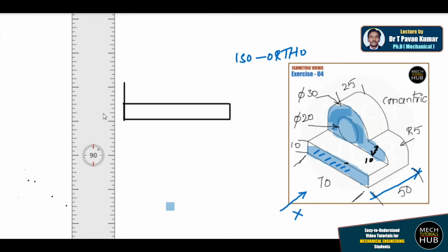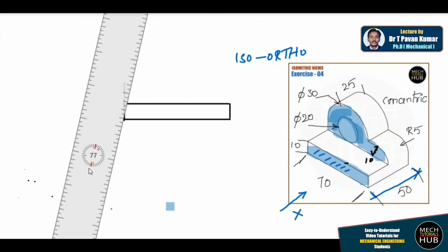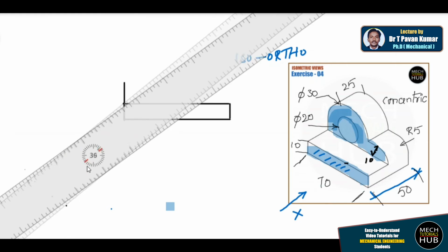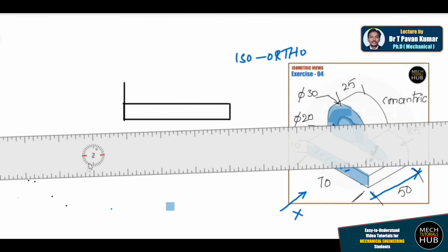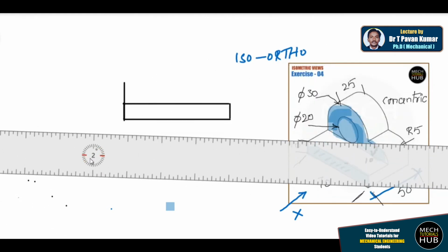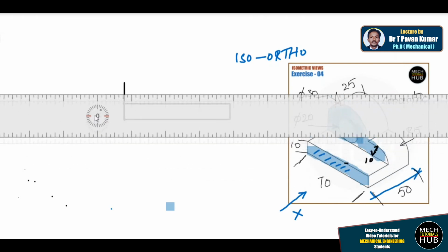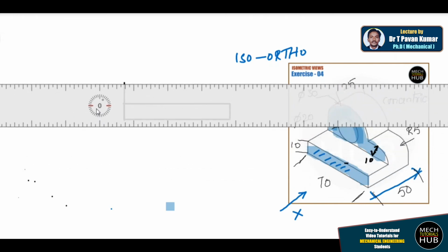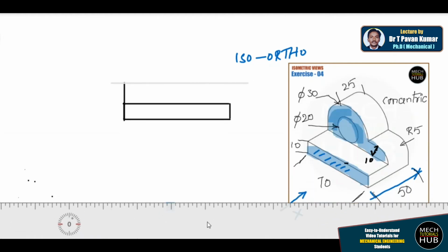after this, with the help of compass, by considering a locus, I'll tell you how to draw a locus line. Locus line is nothing but a reference line which will help you to draw further features or the lines or the links. I'll try to place a scale at the end point of the intersection and try to draw a construction line, nothing but a locus line. This locus will help you to draw a circle with the help of compass.